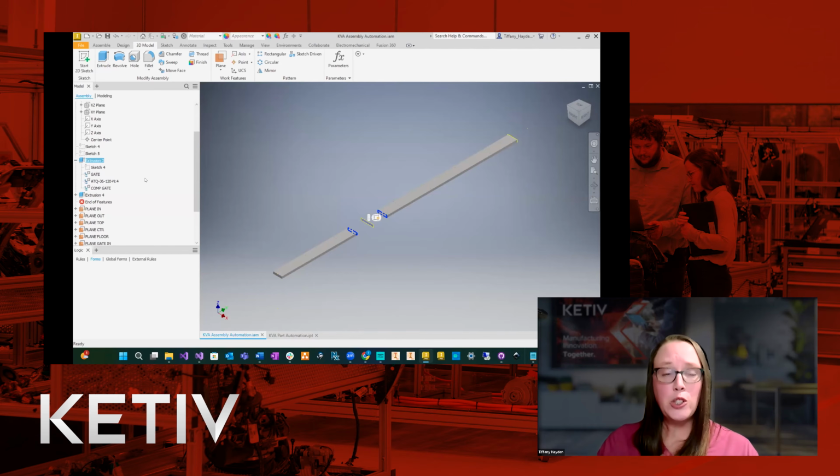But when you do an extrusion and you have material to cut away, it automatically adds certain components as participants to those cuts. So you want to make sure that you're actually cutting away the things that you would like to, because it's going to say, okay, I'm cutting 120 inches, here's all the components that are in that path, let me go ahead and add them as participants to this extrusion cut.